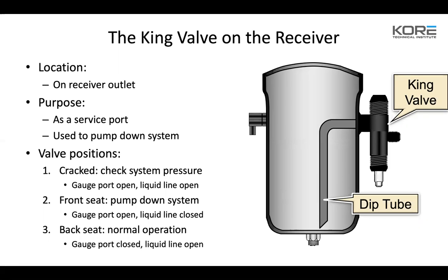The other thing is I've watched guys front seat and back seat, and when they do, they give it a really, really hard turn at the very end, thinking that that's going to do it. What guys are doing is bending the seat inside there. You just need to gently back it off and give it a little snug, just a little finesse. You don't need to get on it like McGill or Gorilla and really get after that thing. I watch guys get on these valve stems way too hard, and you're damaging those valves.